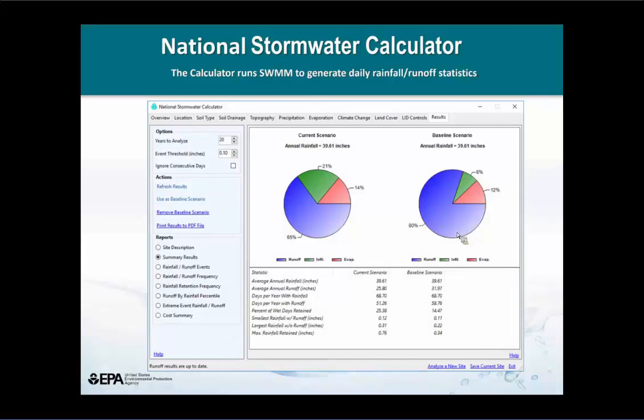The baseline scenario for this case is for Cincinnati, and we get about 40 inches of rain. And if we have a lot of impermeable area, 32 inches of those 40 inches of rain will run off. If we take 70% of the area and put in a porous pavement, instead of 32 inches, we can get 26 inches of runoff. And we can continue to size, add some rain gardens, put in a green roof. We can start to see what we can do with green infrastructure. That probably will not prevent us from having runoff, but can certainly reduce the amount of runoff that we will produce.